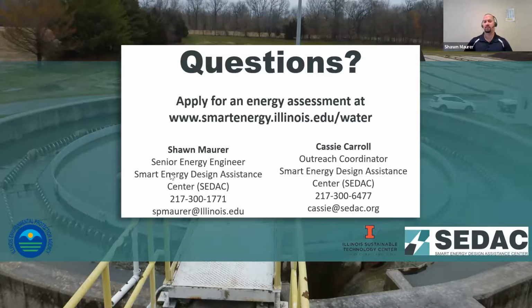Well, it looks like the person who was going to talk about specific energy earlier has jumped off, had to go to another meeting. But specific energy is essentially how many kilowatts you are using per gallon of water that you're pumping. So it takes into account the efficiency of the motor on the pump, the efficiency of the pump itself, and if you've got a VFD applied to it, the efficiency of that. And as you adjust the speed of a pump, you adjust the pump's efficiency in relation to the system curve for your distribution network or your well water system.